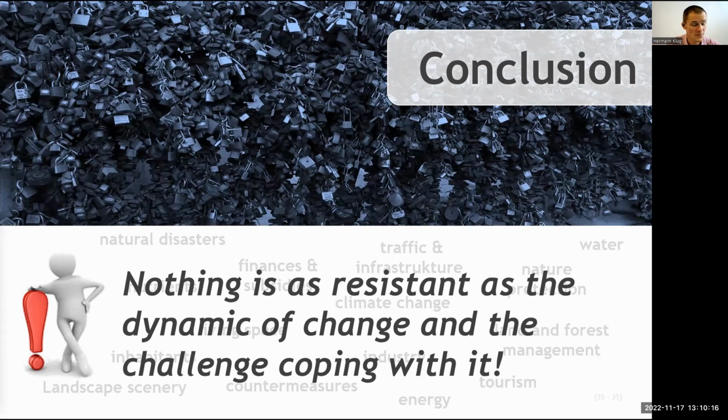But what we could do is say, okay, we know all the other environmental phenomena, like the soil water level, so if the soil's moisture level is at a very high level, even if it is not an extreme event, we'll still have surface runoff. And if we have a certain amount of rainfall, we can calculate and predict how much water is coming together at the confluence points of rivers in a certain time. And then we know if we reach a certain level, then the underlying municipalities will be flooded.